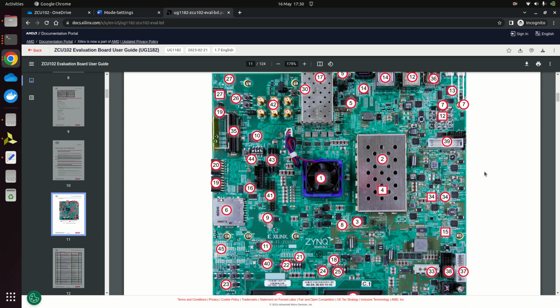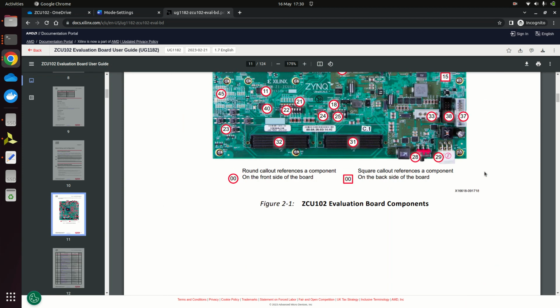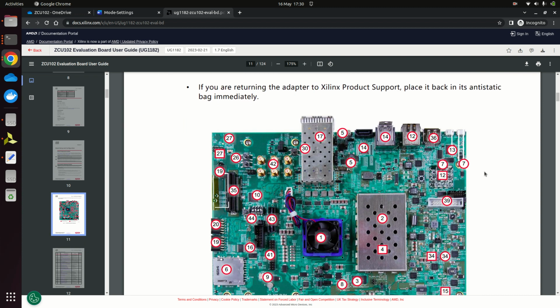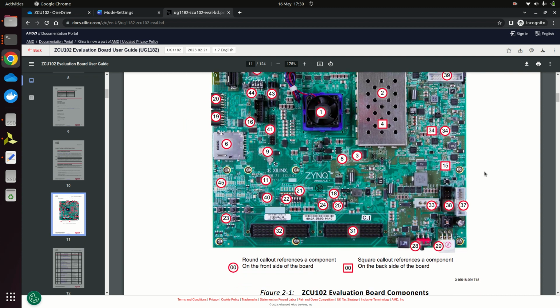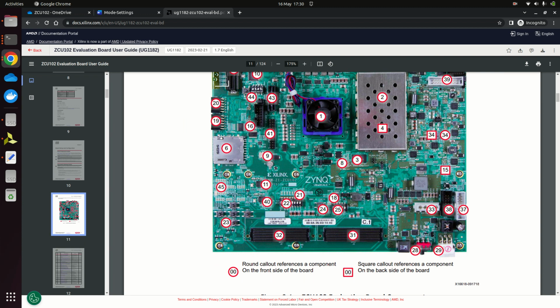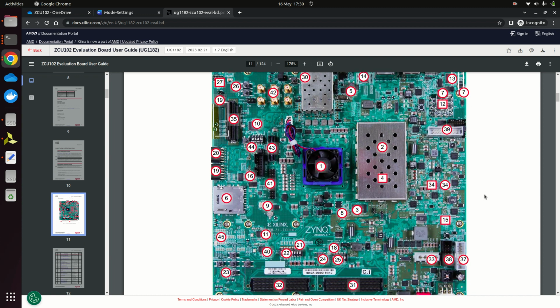Before you proceed to the FPGA board, I would suggest that here is the power connector where you are going to connect the power. But before power connecting it, there are two things when we need to program the FPGA: you can use the FPGA, the architecture that you are designing, or you can go with the existing image of Linux, or you can say PetaLinux, which is installed in this ARM controller.